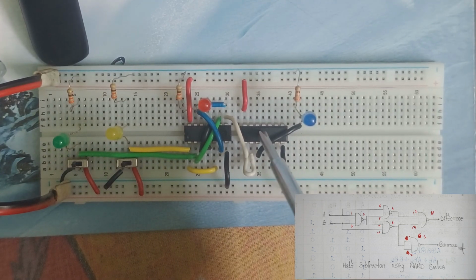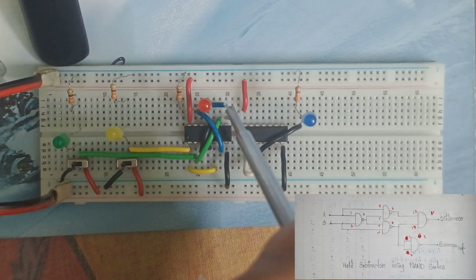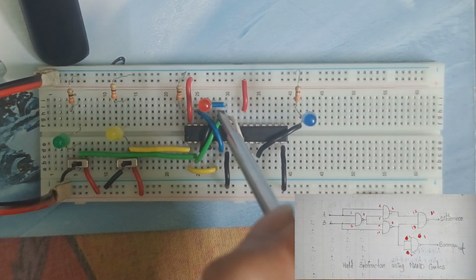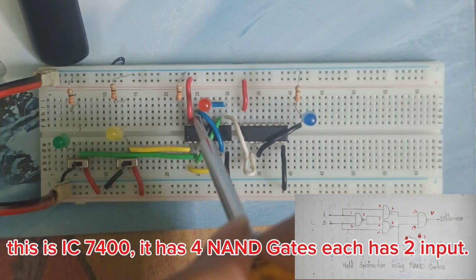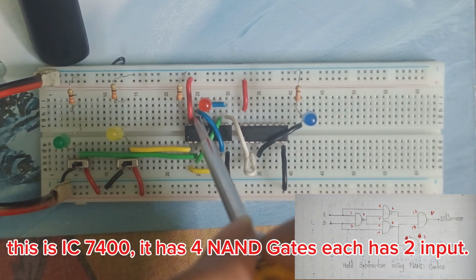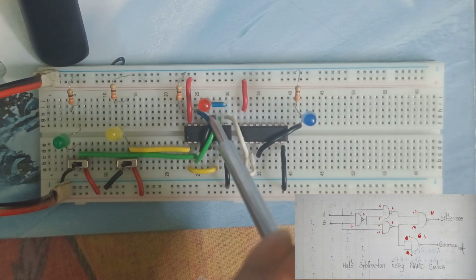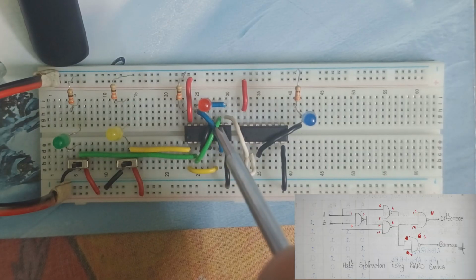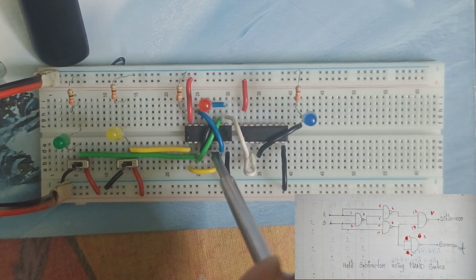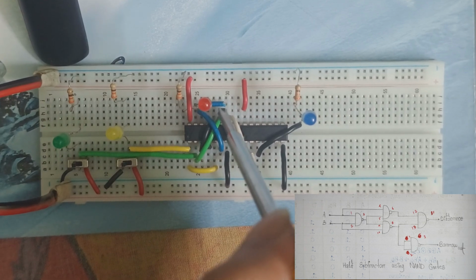I will tell the reason later. So here pin number 13 is connected to pin number 8, which is the output of our third NAND gate, and this is the last or fourth NAND gate of our IC. And this fourth NAND gate is doing the operation between these two blue wires. These two blue wires are the input terminals for this particular NAND gate. This blue wire is getting the signal from the second NAND gate of the IC, and this blue wire is getting the signal from the third NAND gate of our IC.